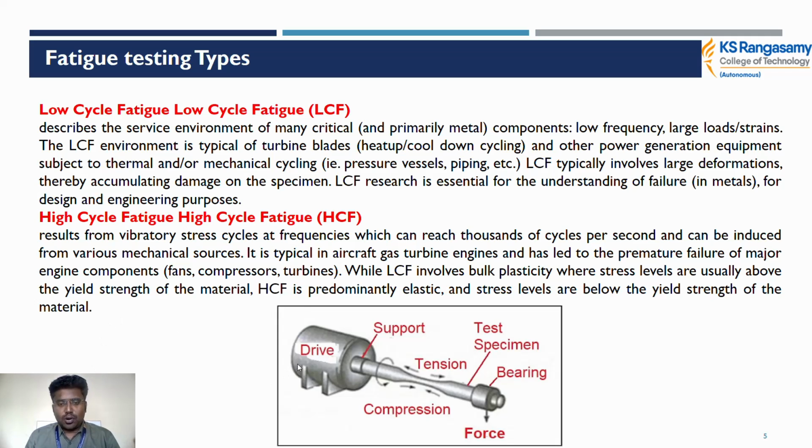So this is the drive motor, where the load initially comes from the driving side. This is a supporting one. On one side there is tension, and on the other side is compression. This is the test specimen. So the load is applied cyclically on the specimen.